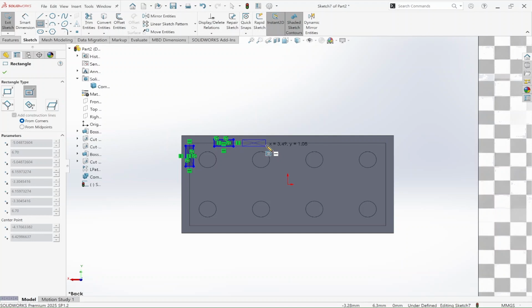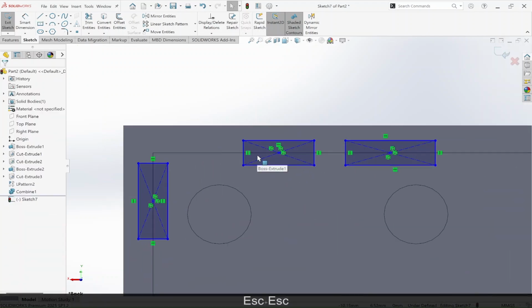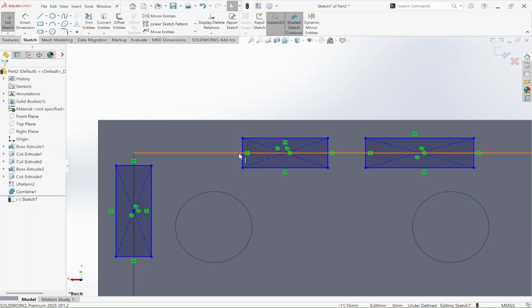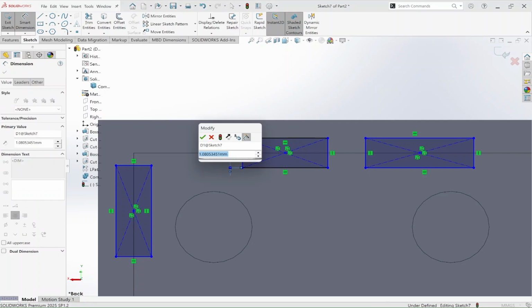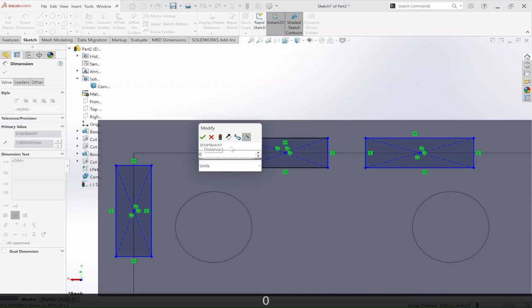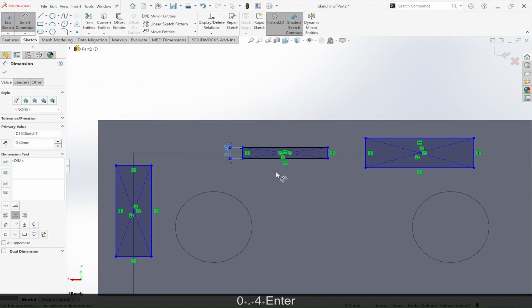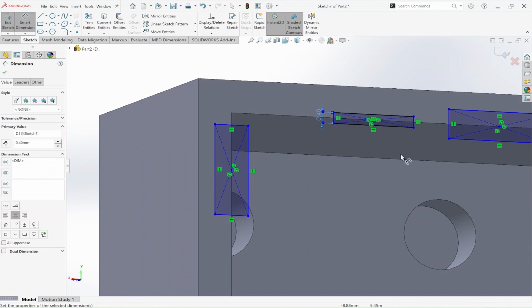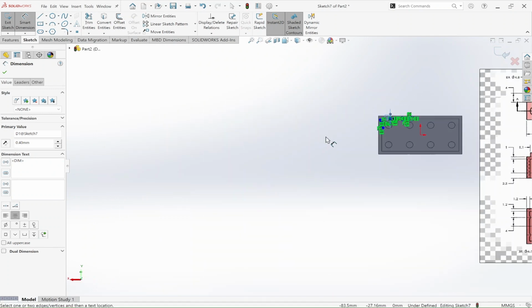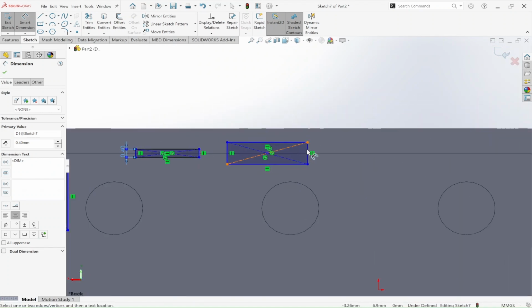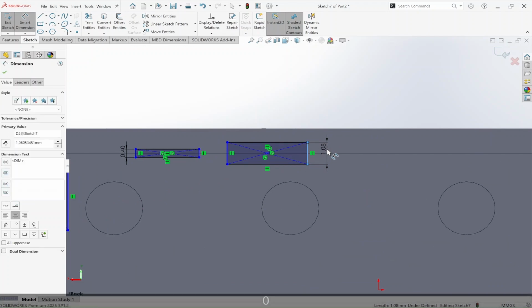Also we need one more here, and now we only want this section, that is after this thickness of this wall. So for that we have to give 0.4. So after that we'll only receive 0.2 mm. We'll give 0.4, so half of that will go into this thickness only. That's why we have given the dimension of 0.4 mm. We'll do the same for this also.